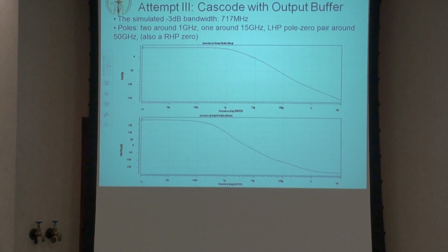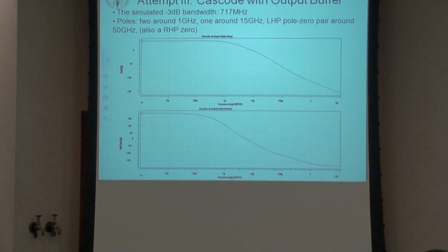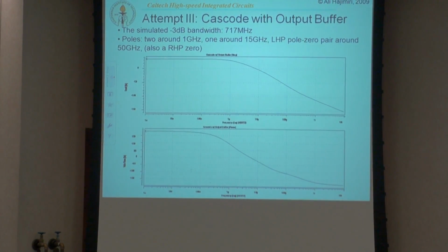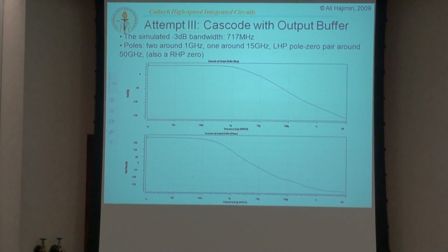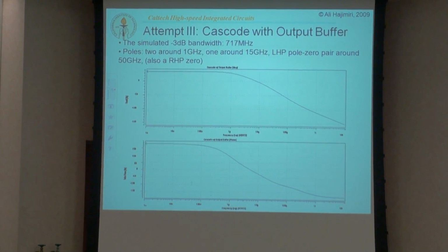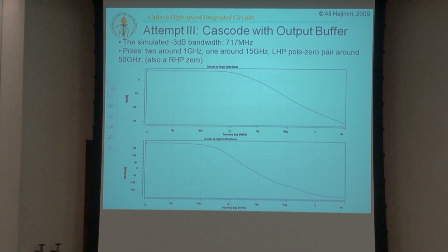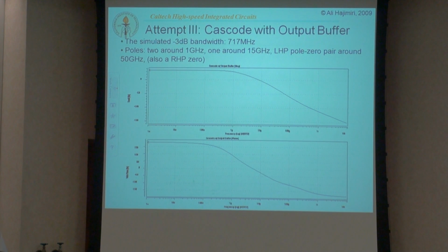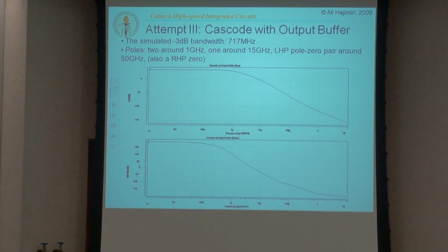So if you take the 700 megahertz, the gain bandwidth product is now closer to the fT than you thought. And you see, the more you push it, the more conservative it becomes. Right? Because you can't make it give you a more accurate result. I mean, you can't make it be on the liberal side. By definition, it cannot be. So the more time constants that you introduce, the more conservative it becomes. So the difference between this and the actual value becomes larger and larger. And I'll show you cases where it becomes tremendously large.